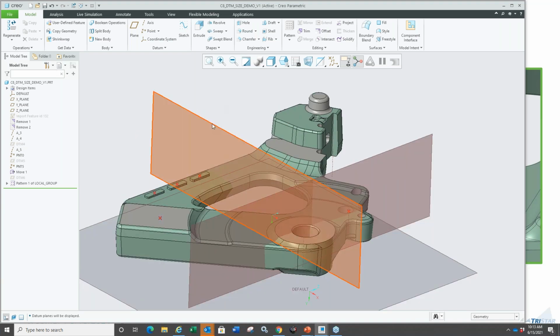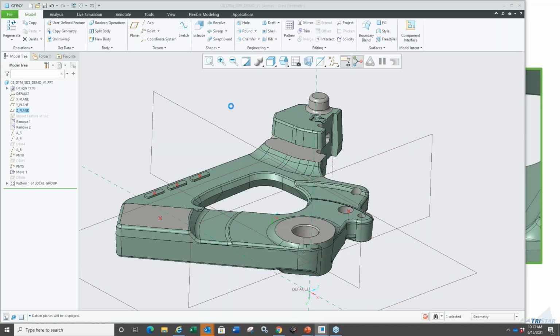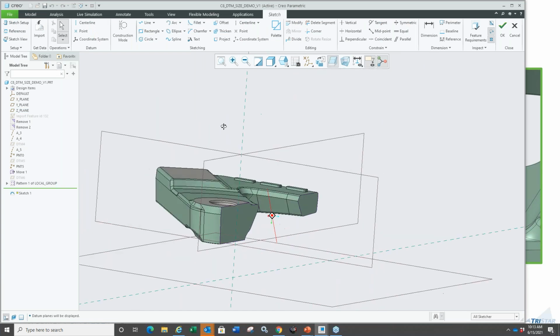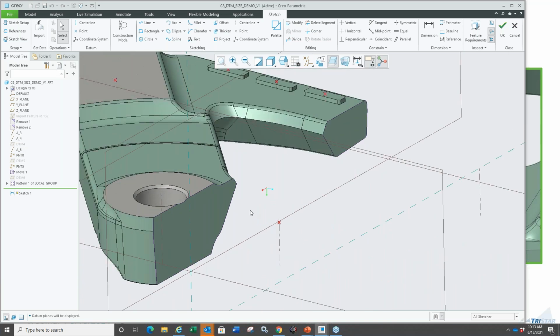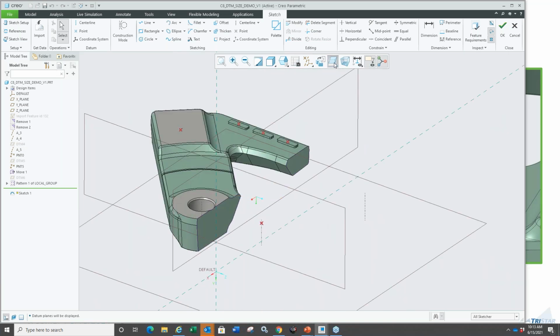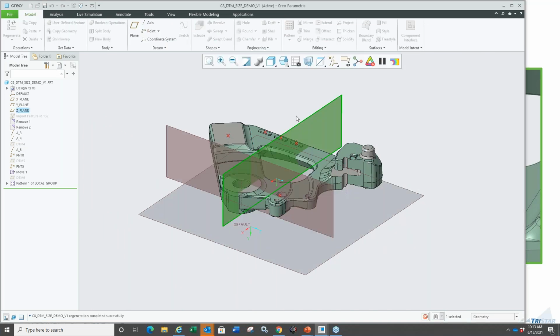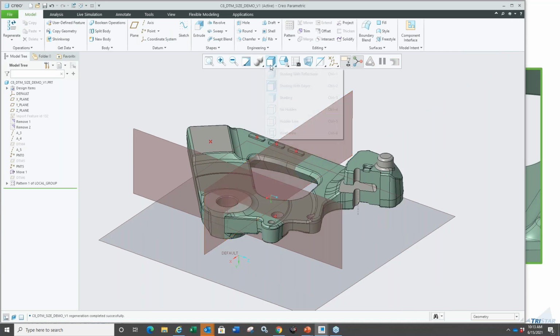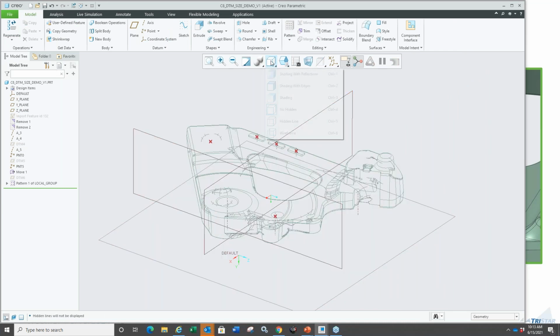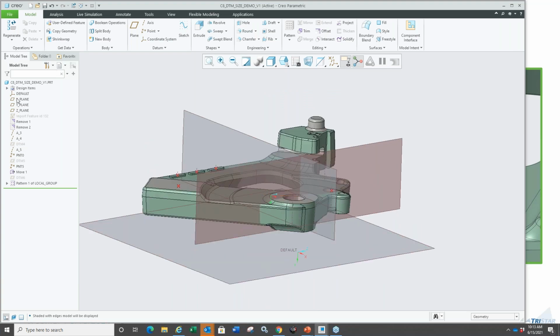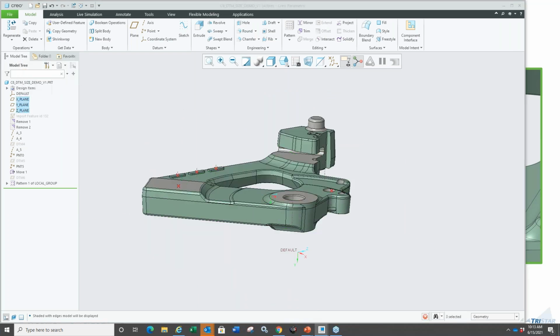And by the way, if I go into sketch mode, I want to sketch on that plane, for example, it's smart enough to take away that fill display. You still have your good old clip modeler they introduced in Creo 4.0. So all that is there, so you can collect references easily, and it's easier to see rather than going to hidden line style, etc. It also removes that shaded fill display when you switch to no hidden style or hidden line style, any of these. When you switch to shading with edges or shading with reflections, it understands to keep that in there. So let me just hide those once again from the mini toolbar.